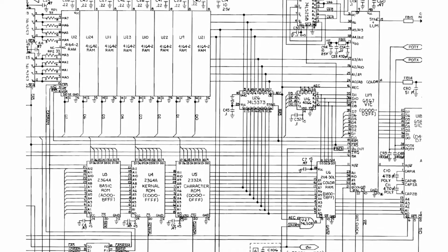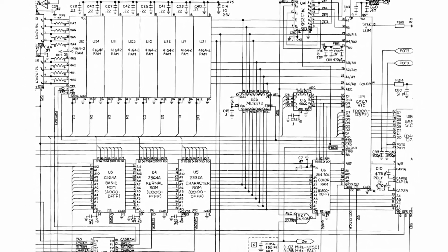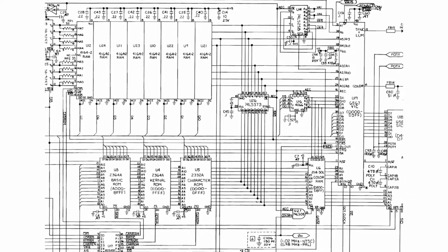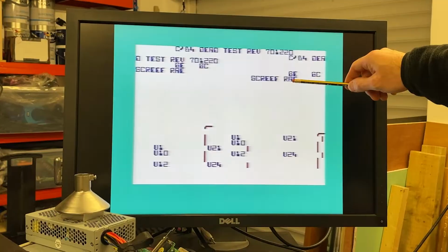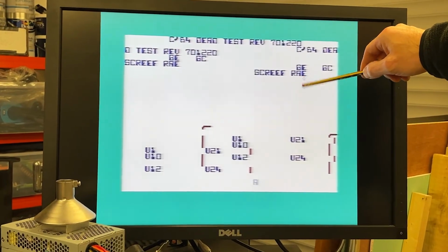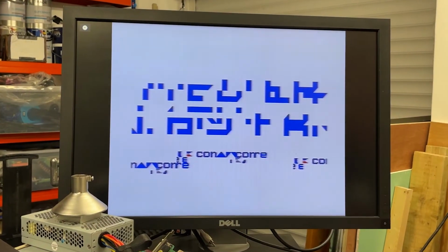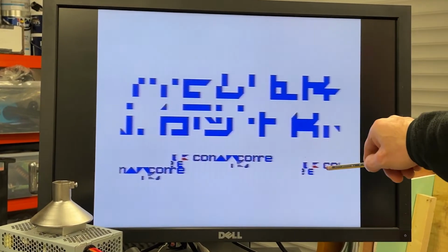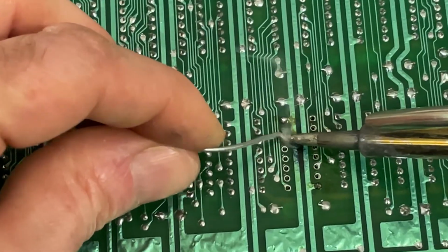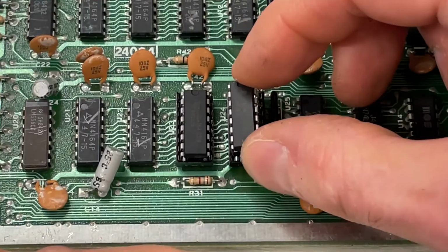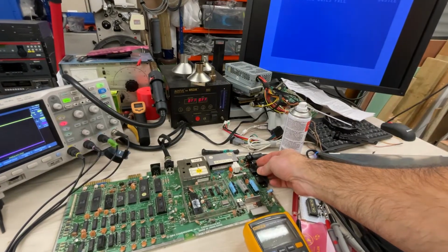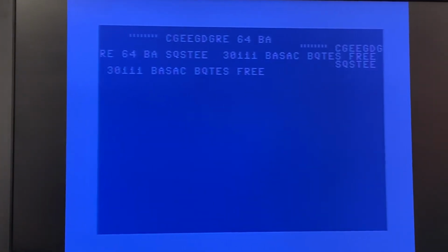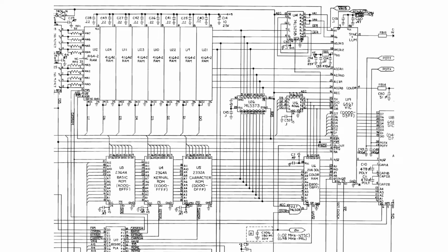I've also rejected the idea that the character ROM may be faulty inside and somehow display the incorrect characters. This is because custom characters also seem to be displayed incorrectly. Jupiter Landing, which is a graphic game, was also all over the place, so that cannot be caused by the character ROM itself. In the past episode, I replaced 2 memory modules based on these likely incorrect assumptions, but the issue was not fixed. So, at this stage, I feel we need to understand things a bit better, and the next question is, how are characters addressed on the character ROM itself?